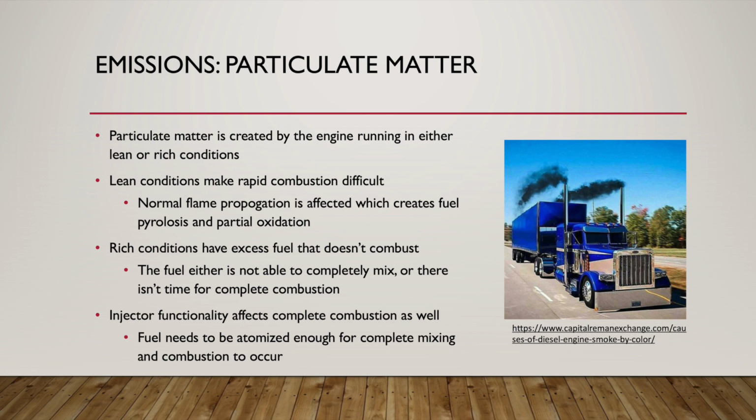Diesel is a liquid, and so that means that we need the fuel to be atomized, to be in the smallest droplets that it can be in, so that we don't have a long droplet time, so that we don't have to wait longer for the combustion process to occur. And so we have to make sure that the injectors are injecting the fuel in as small particles as possible, spreading them out as much as they can, so that when this combustion occurs, and it's very fast, that everything